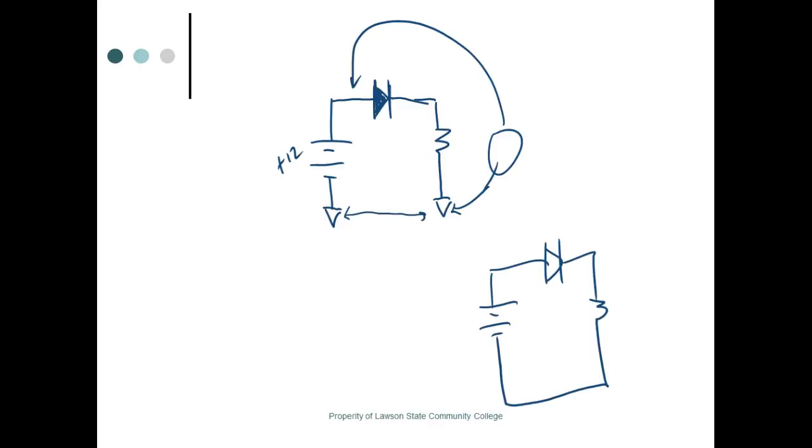This happens a lot in this class where they'll say, well, I thought that was in the trainer. It's common. I thought the wire was in the trainer. Well, it's not. It's a wire you have to hook up that we're representing with a symbol, right? You understand. But it usually means we make all our measurements relative to common.